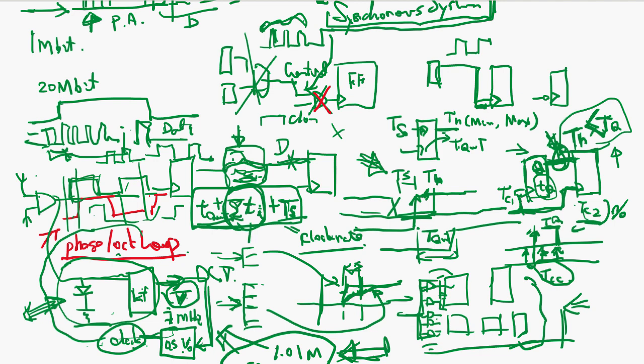And in this case, you find the longest path, the longest time it takes from here to here, and that defines the critical path in the logic design. This is very important, and that's a way you can improve the clock rate for your chip design.